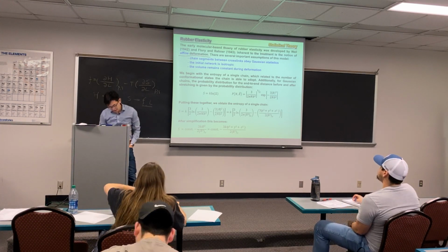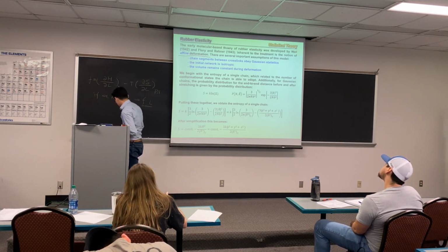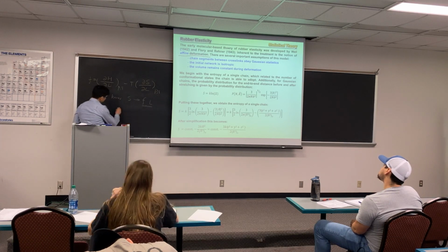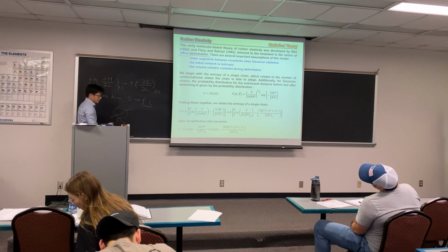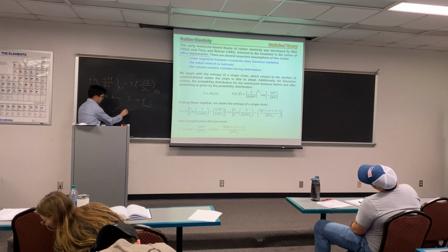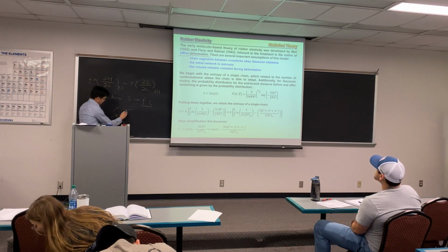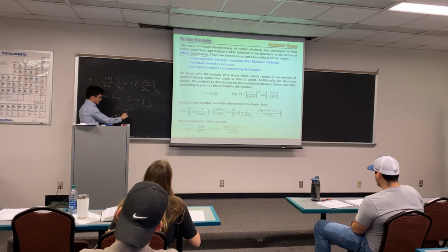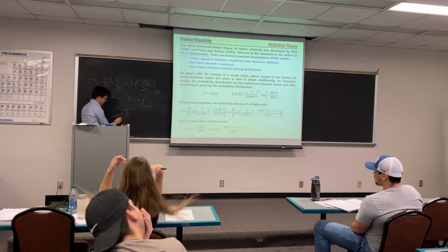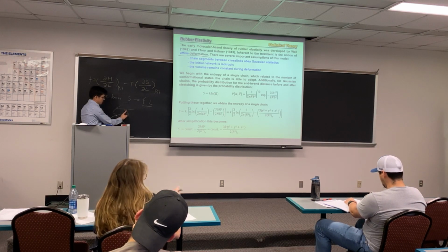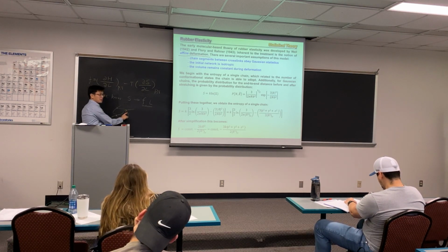As well as, the chain segments between the crosslinks obey Gaussian statistics. This is a little bit simplified, but you can think about these as crosslink points. And I'm drawing this quite simply, but what the rubber elasticity theory states is that between each crosslinked point, your polymer chain will be a Gaussian coil again.